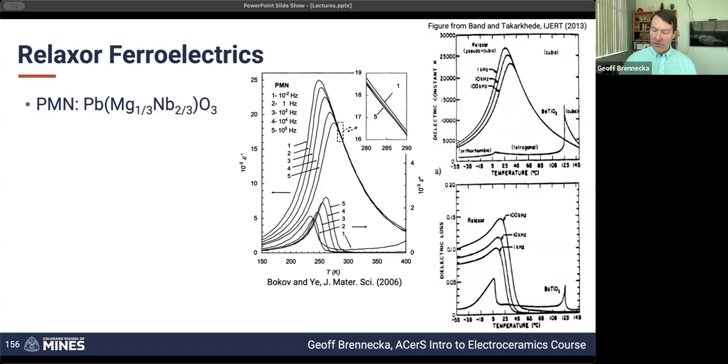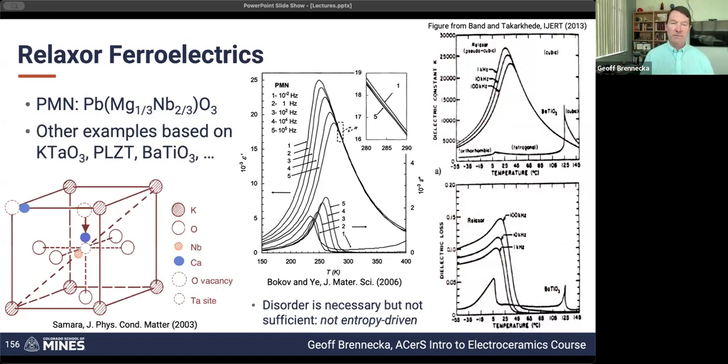So the other aspect is when we look at the dielectric loss, so tan delta, we see as we looked at before, barium titanate has peaks in its dielectric loss whenever it goes through these phase transitions. These relaxer materials have a much higher loss when they're in this disordered, messy, who knows what's going on sort of state than when they're above that permittivity max and everything collapses down. We also see a large frequency dispersion in that lower temperature region. So what's actually happening in these materials?